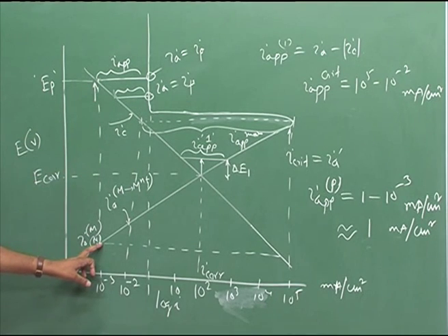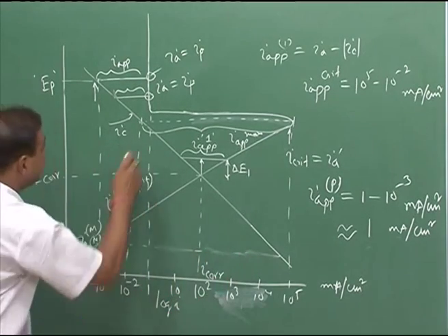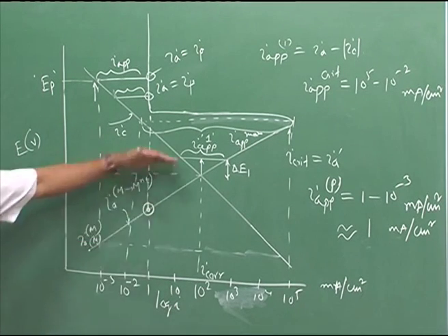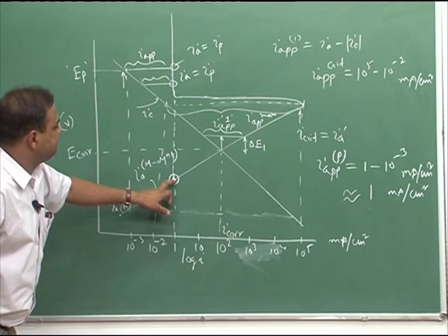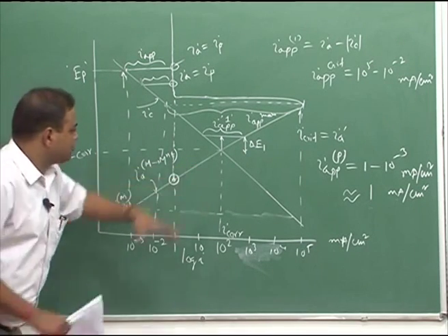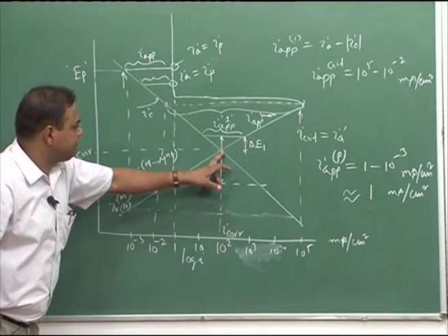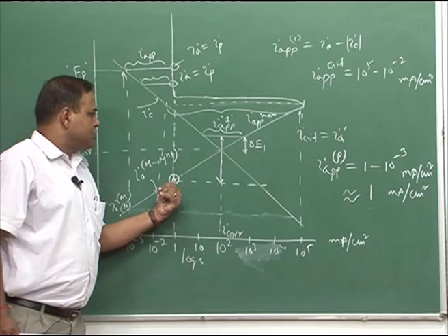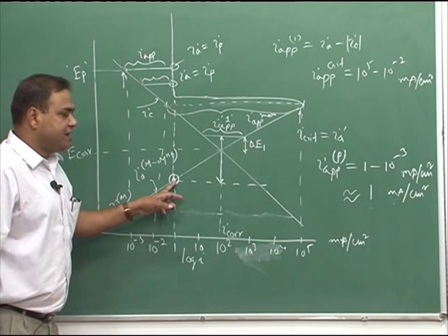this much current density, if I go cathodically, if I protect this material cathodically, then the same current density level I would like to achieve. So, I need to go up to this point. So, the negative polarization I have to give of this value, that time I can experience my current density corresponding to this much current density, and this is also IA at this point.